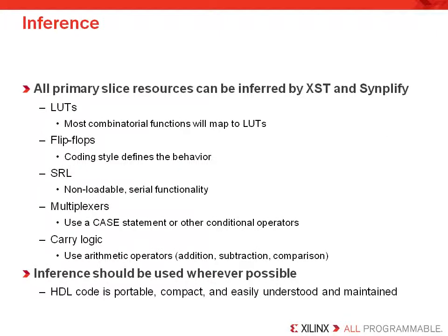All primary slice resources can be inferred by XST and Synplify. This includes LUTs, flip-flops, the shift register LUT, muxes, and carry logic. However, you must be sure to code for the resources properly. This means that if you define a flip-flop with an incompatible combination of control signals, you may get something slightly different, maybe a LUT input used for a control signal.